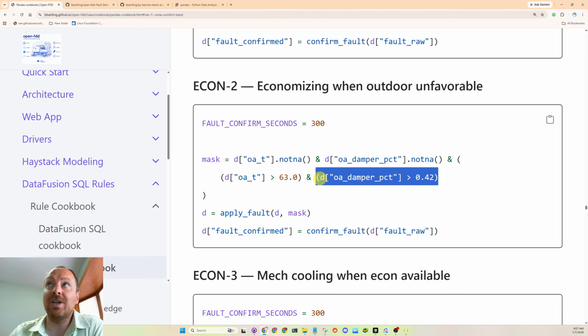What always happens is there is a test and balance contractor that sets that for whatever the mechanical engineer designed as the minimum ventilation for people to breathe. So that's set and measured by a test and balance contractor. And then what happens all the time, very commonly, is the maintenance staff monkeys with the set points over time. So keep that in mind too.